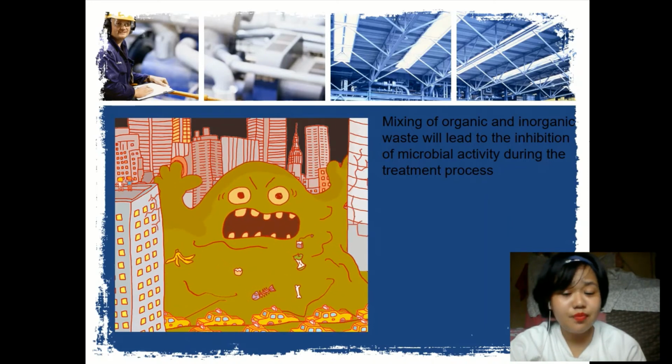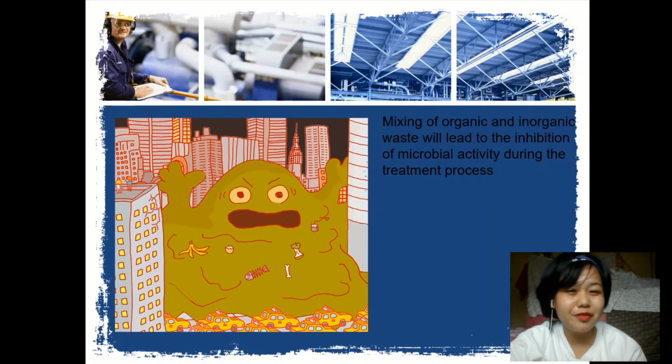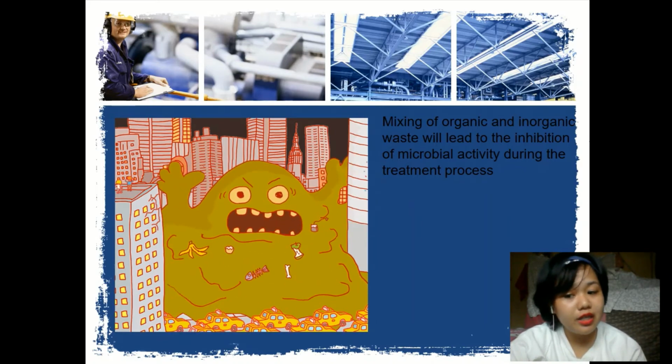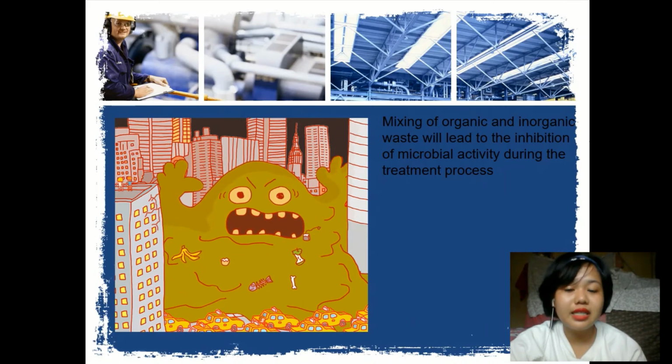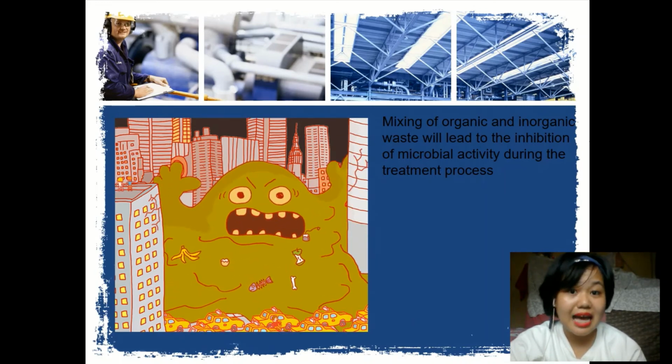That's why it is important to segregate the wastewater streams into a number of streams in complicated processes such as oil refinery or integrated steel plants, and then treat the individual streams as necessary.